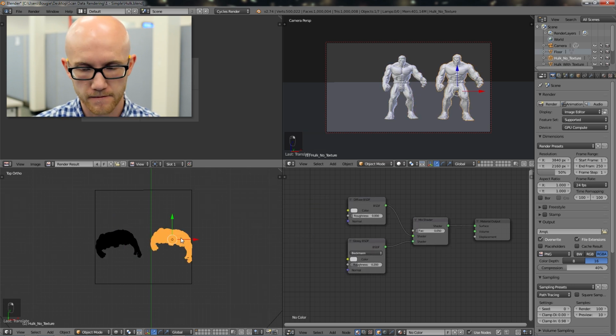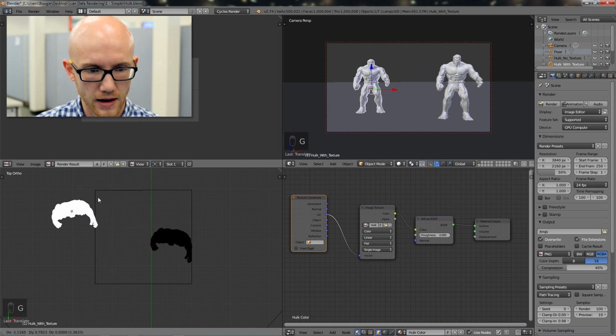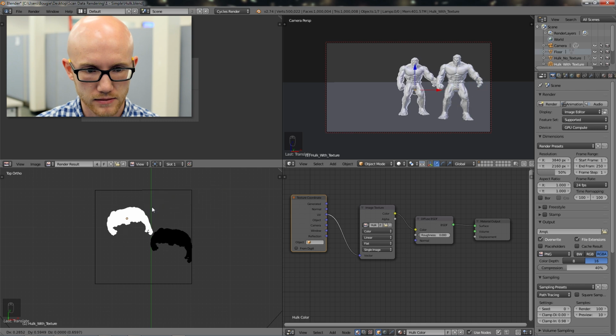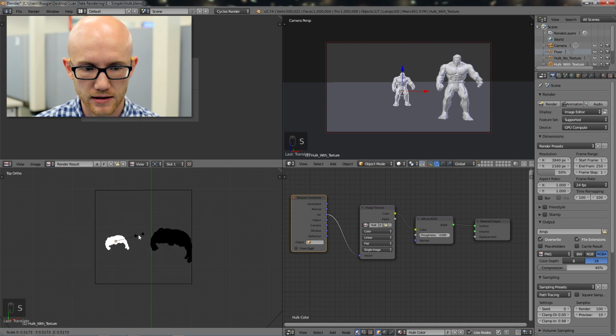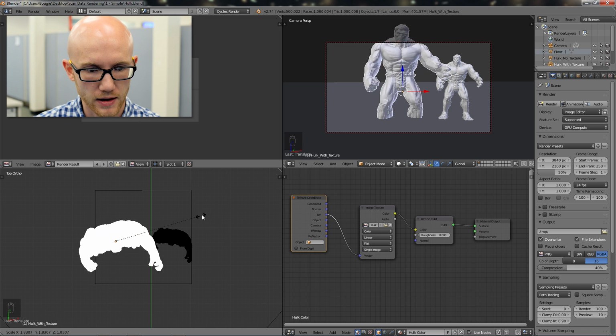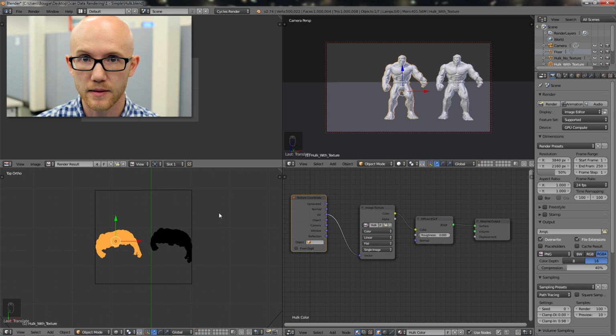All right. So that's the general controls in Blender. If I select an object here, I can press the letter G, and that will grab it and let me move the object around. If I left click, it will place the object. If I hit escape, it will put it back where it was. While I have an object selected, I can press the S key, and that will let me scale the object up and down. Make it bigger or smaller. Again, if I left click, it will place the object. If I press escape, it will put it back the way it was.